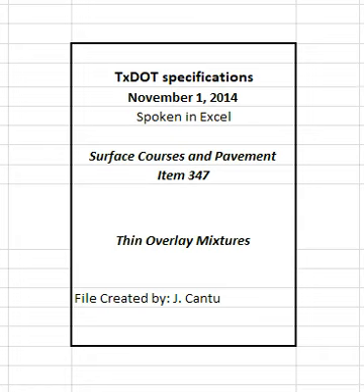Place the mixture to meet the typical section requirements and produce a smooth, finished surface with a uniform appearance and texture. Place mixture so that longitudinal joints on the surface course coincide with lane lines, or as directed. Ensure that all finished surfaces will drain properly. Place the mixture at the rate or thickness shown on the plans. The engineer will use the guidelines in Table 9 to determine the compacted lift thickness.